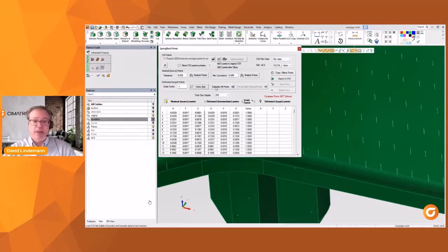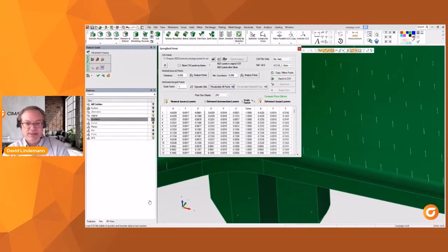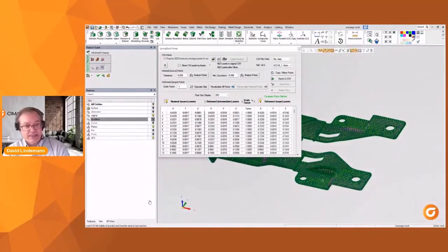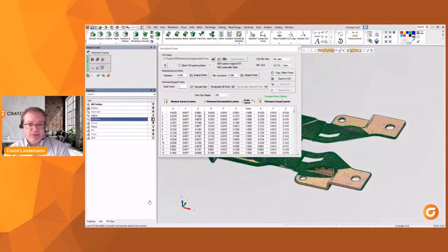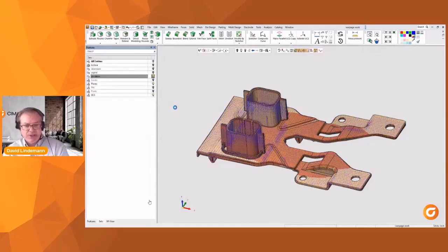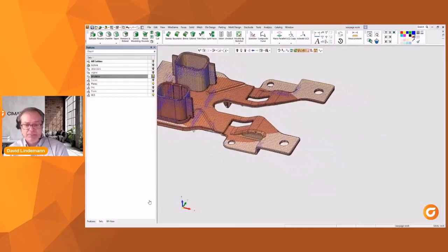Okay, so while the part may bow in or up, now we want to compensate by having it bow down or out. So we're going to get the opposite effect of the STL, and that's the information we're looking for. So think of all the little measurements you would have to take to find how much it's varied in warpage from the original to the STL file, and now reverse all those, and now model the part based on that. Again, that's a huge amount of work that has confronted the industry here. So we'll go ahead and run the calculation, and this gives you an idea how long it takes. For as much work as it does, it's not really taking a terrible amount of time.